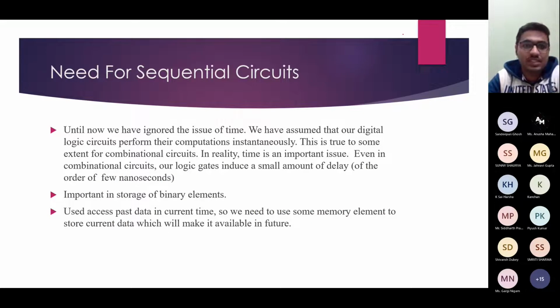Need for the sequential circuits. Until now, we have ignored the issue of time. Also, we have assumed that our digital logic circuits perform their computation instantaneously. This is true to some extent, but in reality, time is an important issue. Even in combinational circuits, our logic gates introduce a small amount of delay, which is on the order of a few nanoseconds. Also, sequential circuits are the only thing which can store binary data.